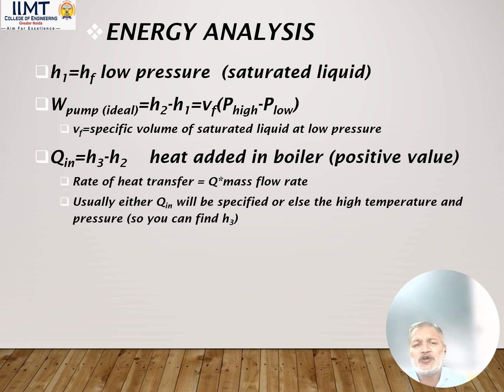Similarly, heat addition in the boiler. What is heat addition? When water enters the boiler with a certain enthalpy, and we heat the water, after heating, saturated or superheated steam is generated. So the enthalpy of steam minus the enthalpy of water gives you the heat addition in the boiler.